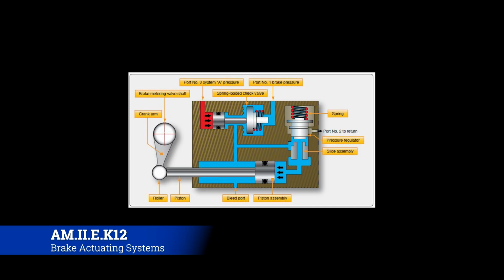Following down, we'll get to the power brake control valves. Those are valves that make the decision of how much pressure gets applied to the actual brake assemblies, based on the control inputs coming from the cockpit. So if you have full braking pressure in the cockpit, those valves will be open wide. If it's just a little bit, they'll open just a little bit. Very simple construct, but with very important consequences in the amount of braking that gets applied. The anti-skid control valves are right there.